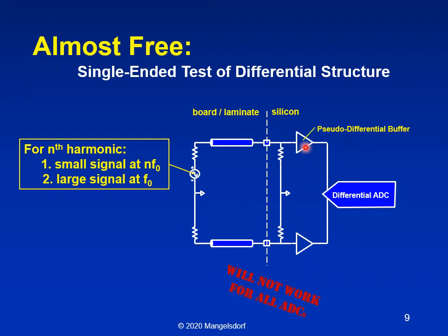So the signal path going to the ADC probably has circuitry which is what we call pseudo differential. It is the same on both sides, but it's not strictly differential. It's two parallel paths that are carrying signals in kind of opposite phase, basically.